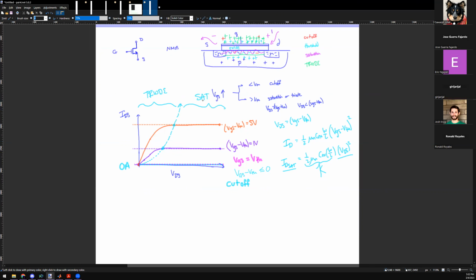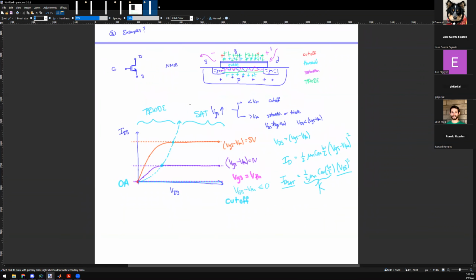So when I say saturation, what is being saturated? In your own words, what is being saturated? The channel, exactly. So if it's easier for you, call it channel saturation. The MOSFET is operating in saturation, but you could put the word channel saturation, and that might help you remember what's actually physically happening. It's like traffic. Basically, there is bumper to bumper traffic inside the road. And that's what we mean by channel saturation or traffic saturation or roadway saturation.